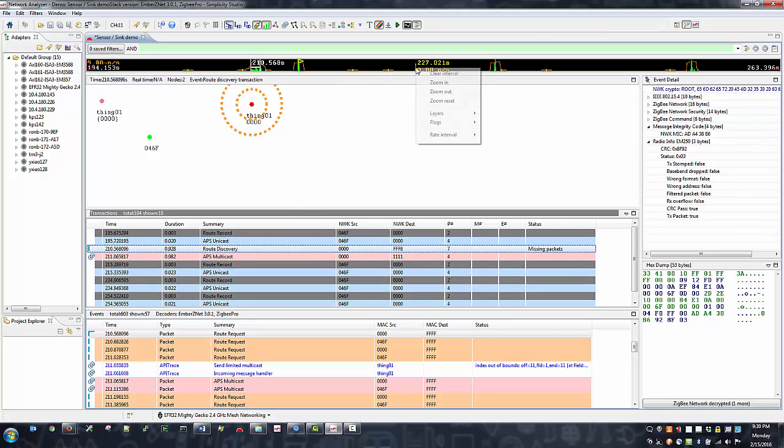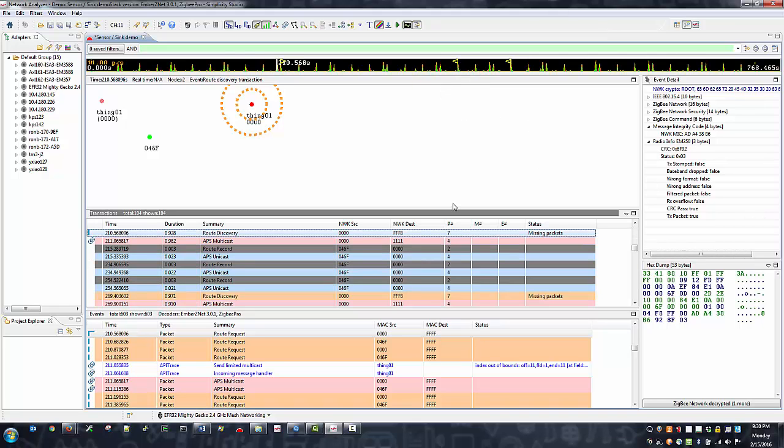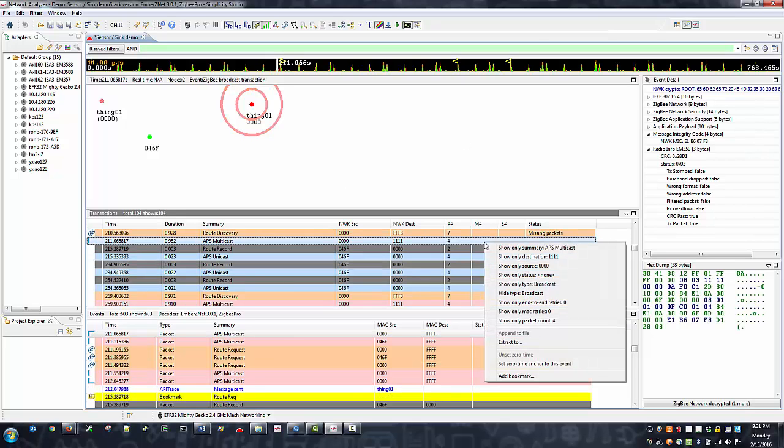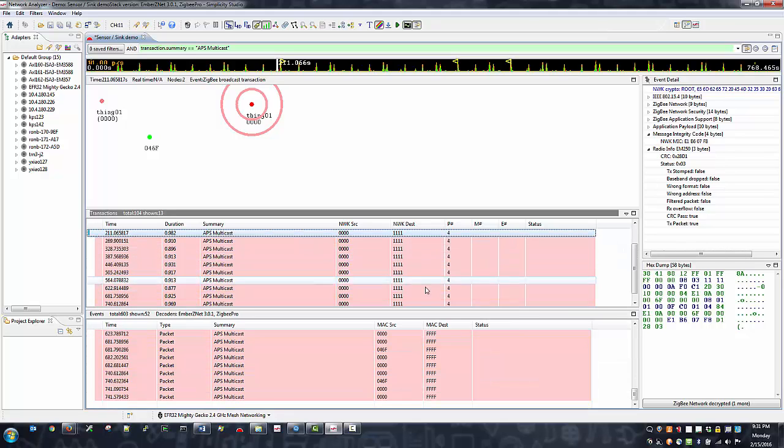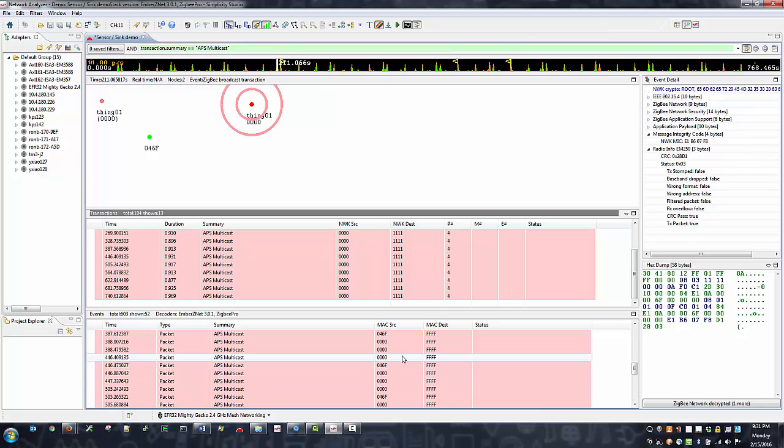And when those long-running captures collect thousands of packets, you'll be glad to know that our network analyzer offers a sophisticated set of filters that can be applied to any part of a transaction or event just to find the data that's of interest to you. Filters can be applied to live or pre-captured traffic and can be entered via the expression filter by selecting one of the suggested filters in the context menu of the Transactions or Events pane, or by manually entering or editing text in the filter bar.